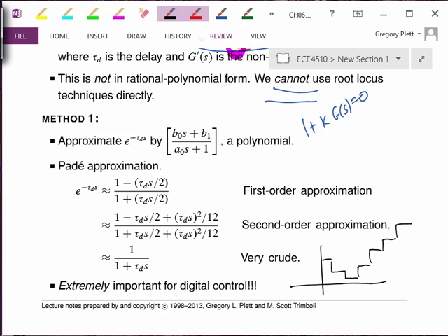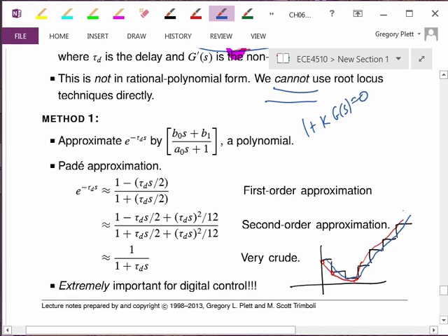And this hold, if I compare the signal that it's holding, which is going through the leading edge of these things, and what it kind of looks like on average, the average signal looks like a delayed version of that. And so using a root locus with a delay in it will help us understand what the actual controlled system will look like better than if I don't include the delay.